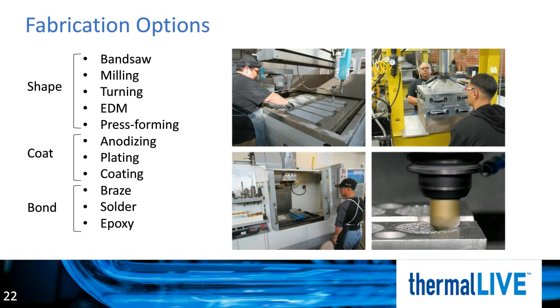Surface treatments can also be applied to the metal foam and include anodizing, plating, and chemical conversion coating. For example, surface treatments that work for 6000 series aluminum also work for Duocell metal foam made from 6000 series aluminum. Duocell metal foams can be integrated into the final product or housing via processes like brazing, soldering, or epoxies.